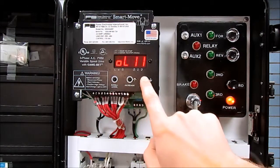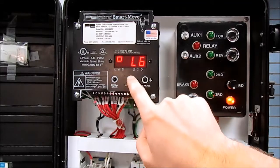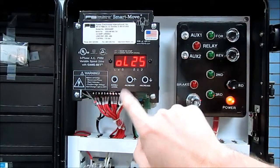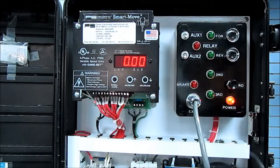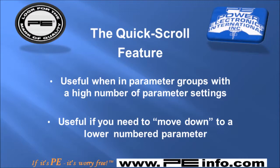Instead of repeatedly pressing the scroll button to get to your parameter, you can now use the increase and decrease buttons to get to the desired parameter number. Once you arrive at the desired parameter, poke the scroll button once, and then adjust the parameter value as usual. The quick scroll method is especially useful when you are in a parameter group with many parameters, and also if you need to move down to a lower numbered parameter.